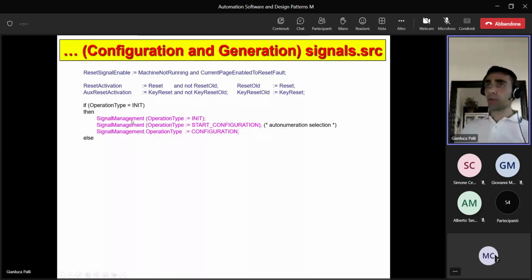We perform a single call of the signal management function block with the operation type init if we need. Otherwise, we can skip this. We make a single call of the signal management function block with the operation type start configuration to reset the information. Then we set the operation type to configuration. But note, we are not calling the function block. We are just setting the operation type input to the configuration value. It means from now on, if we don't change this input, the signal management function block will work in the configuration phase every time we call it.